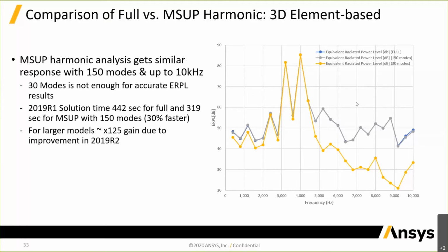So I'm putting a lot of information on this modal superposition setup. And what this gets us is that it is much faster to solve many frequencies and many speeds. And it's even faster in 2020 R2 or 2020 R1 for both object-based forces and element-based forces.